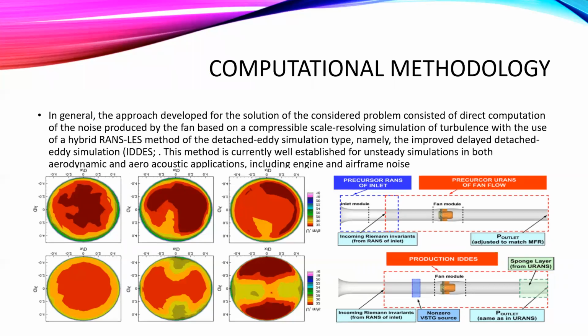Fans are at their quietest when operating at peak efficiency. Bends and dampers close to the fan are common noise reduction features. Simple methods using 2 to 3 duct diameters of straight duct between any feature that is disturbing the flow and the fan itself can cut down the noise by up to 12 dB.